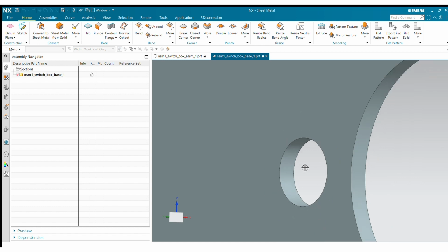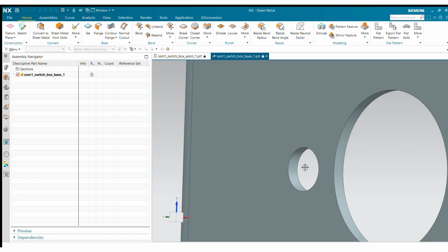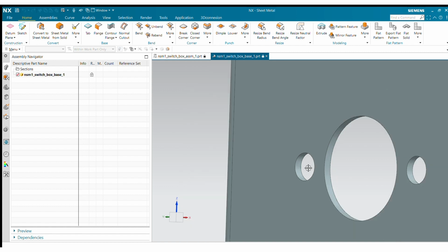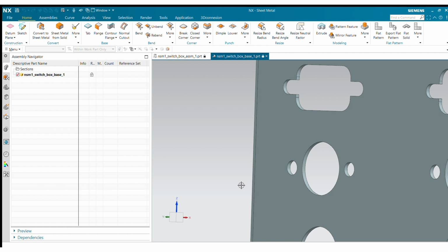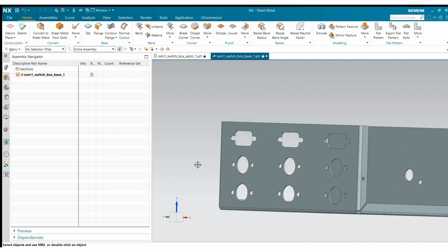Right? So this is how to do it in the part level, and so once you have this set here, when you go to your assembly level and you hit show exact, or if you fully load or partially load, you'll be able to see your exact geometry with your edge accuracy settings enabled. Okay. So this is a quick guide on improving edge display quality, reducing those tessellations that usually show up in larger assemblies.